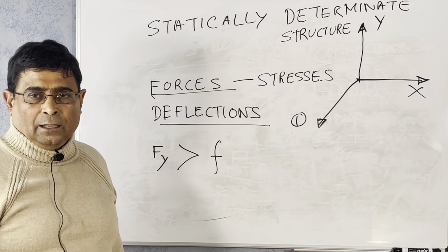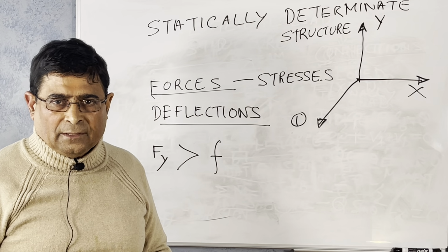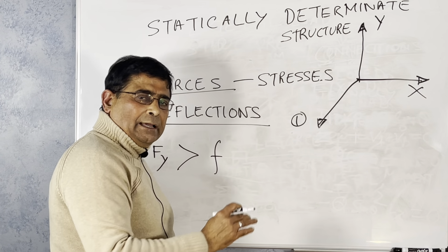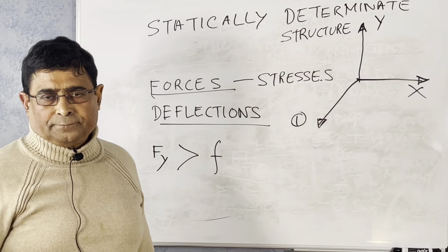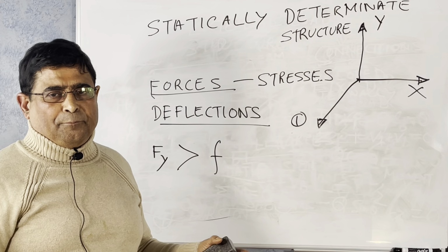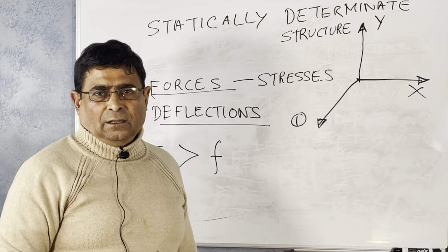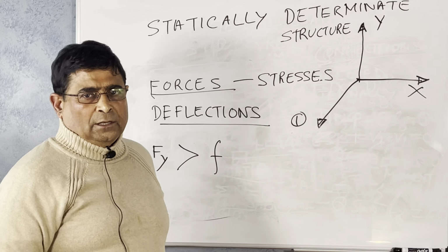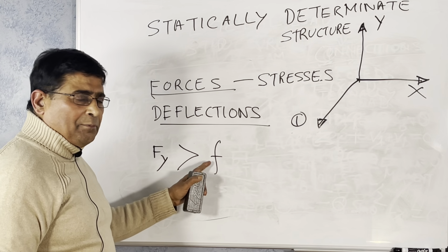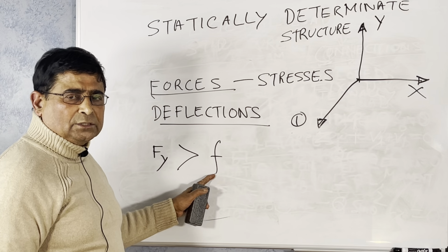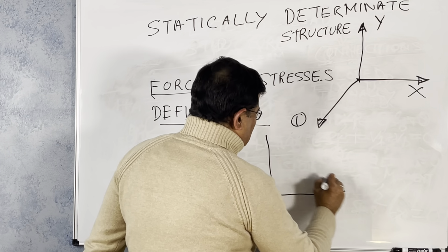Yield stress of steel. Why am I considering steel? Steel is a widely used material in structural engineering, because steel itself is used as a steel section, or steel is a part of reinforced concrete. Mostly we design the beams and others as under-reinforced, so that there is no sudden collapse of the concrete. Many of you know it. So there we prefer yielding. Again, the stresses developed in the rebar, the reinforcing bars, should be less than the yield stress.